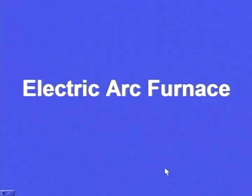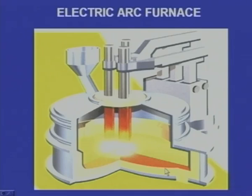Next one, let us see the arc furnace. So this is the cut sectional view of the arc furnace. Here we can see the electrodes, graphite electrodes, and this is a shell, and inside there is a charge, a metallic charge which we want to melt. The power supply is connected between the electrodes and the charge, and we strike these electrodes against the charge and sparks are created and that continues into an arc, and because of this arc the molten metal is prepared, the charge melts. So this is the principle of the electric arc furnace.